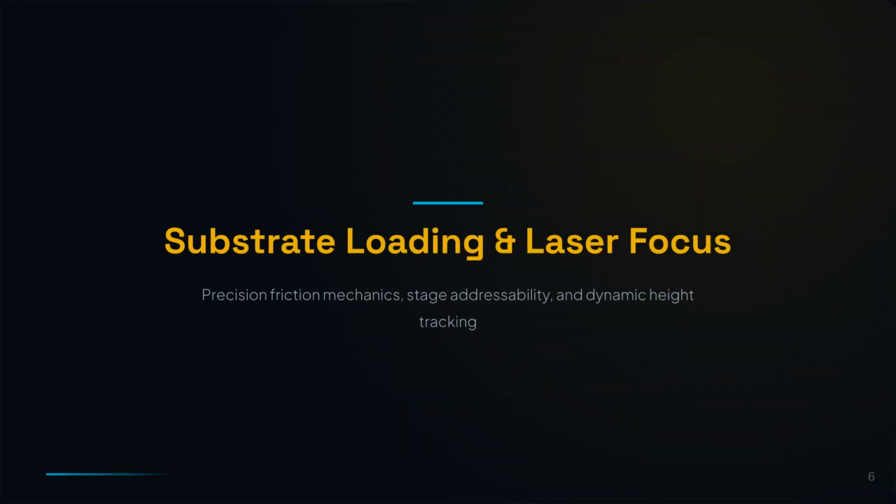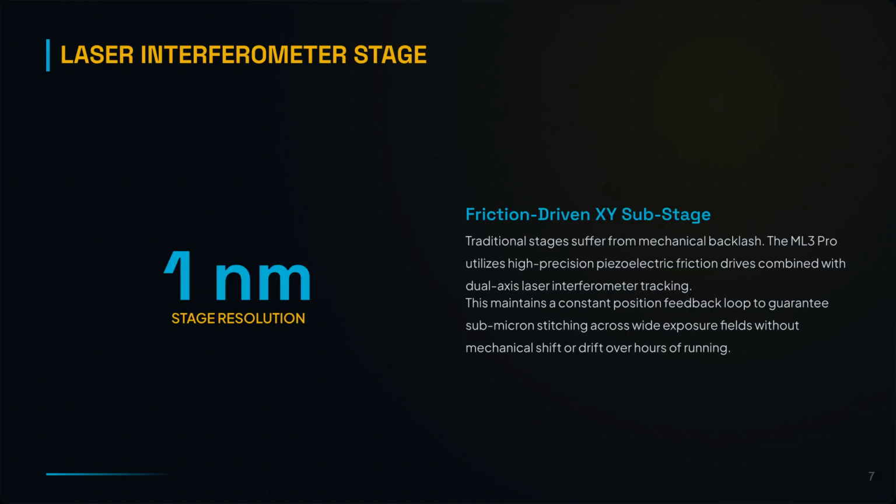Moving on to substrate loading and laser focus, which involves precision friction mechanics, stage addressability, and dynamic height tracking. The ML3 Pro features a laser interferometer stage with 1 nanometer resolution. Piezoelectric friction drives and position feedback ensure submicron stitching across wide exposure fields without drift.